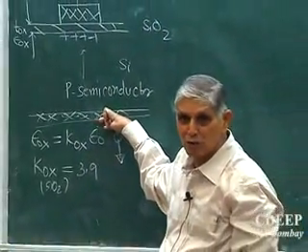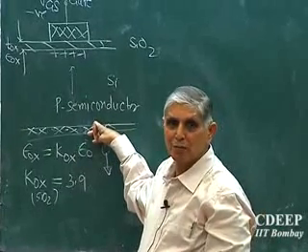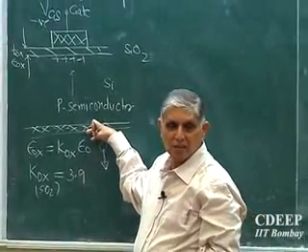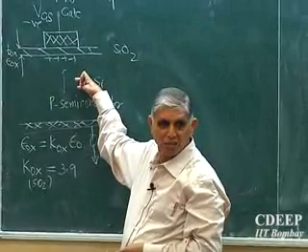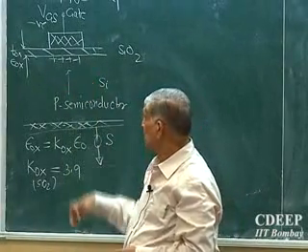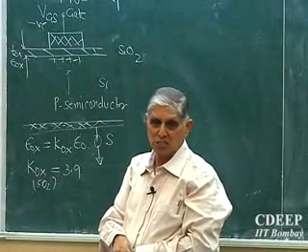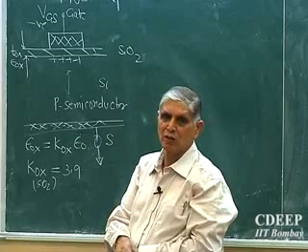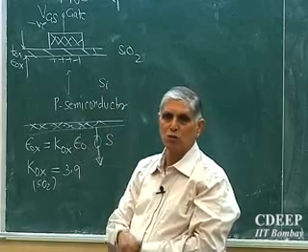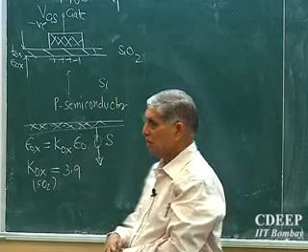They are not depleted out of this. These will be provided by the battery. Is that clear? And therefore additional holes can be created. We say this is a case of accumulation. The larger the minus VGS value, the larger the number of holes that will start appearing.